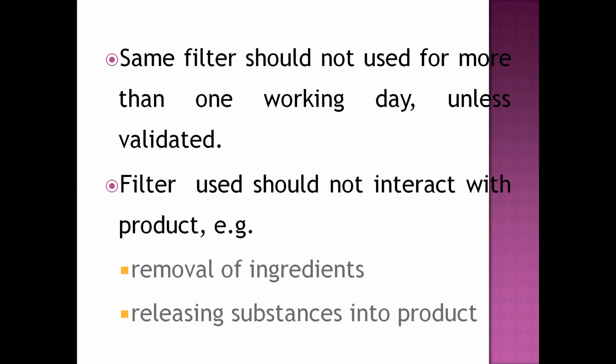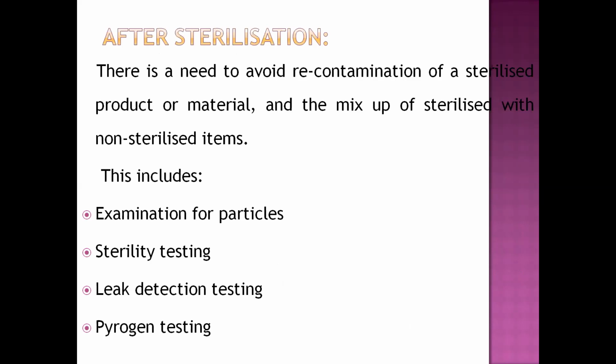The same filter should not be used for more than one working day unless it is validated, and filters should not interact with the product. That means, for example, removing ingredients or releasing substances into the product. Those are challenging areas.